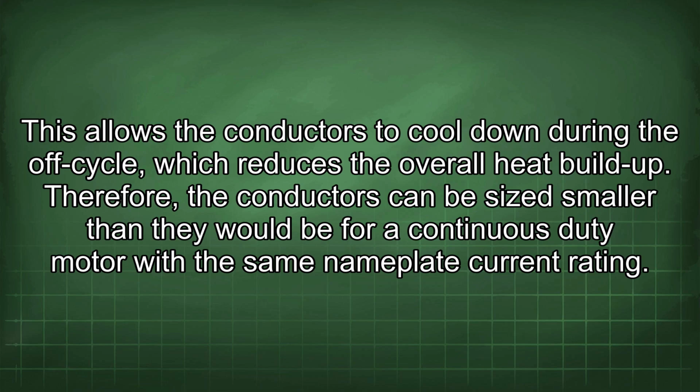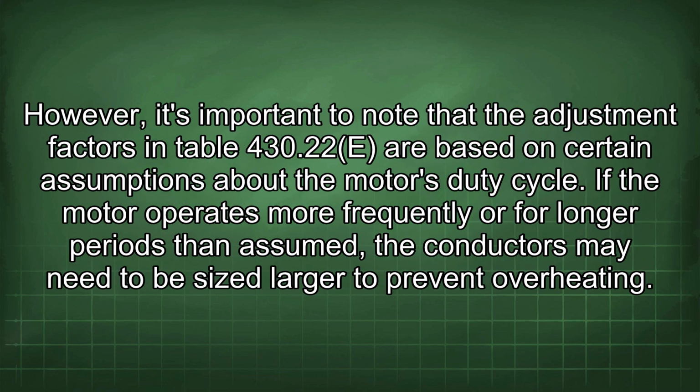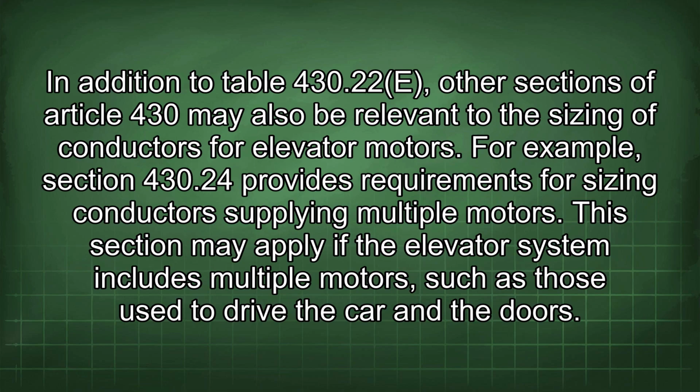However, it's important to note that the adjustment factors in Table 430.22(E) are based on certain assumptions about the motor's duty cycle. If the motor operates more frequently or for longer periods than assumed, the conductors may need to be sized larger to prevent overheating.